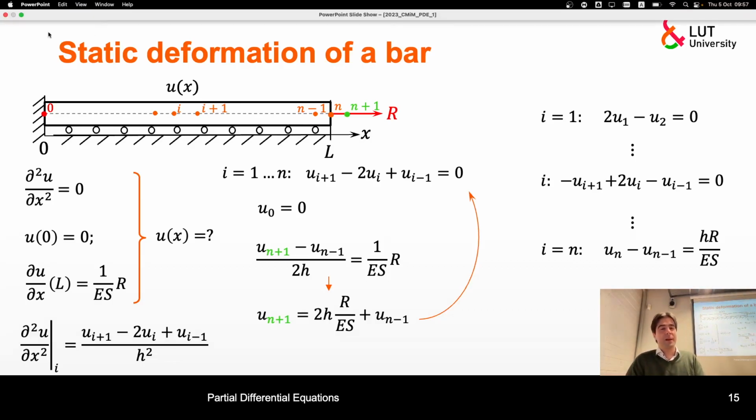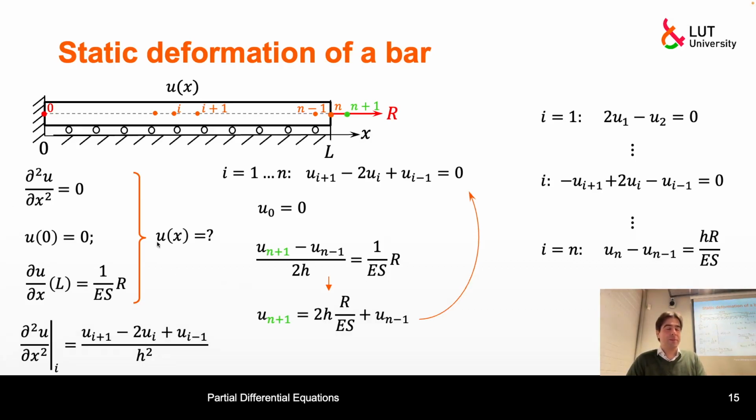Okay, but how do we deal with it formally? So this is our equation, and we have boundary conditions on the left and right ends. On the left end is a prescribed displacement, and on the right end it's a prescribed force. And that is how we can deal with it, because I implied here Hooke's law, that stresses are connected with strains.